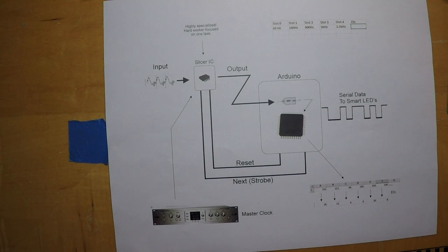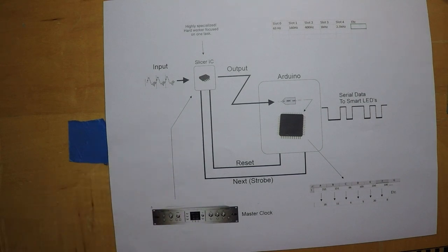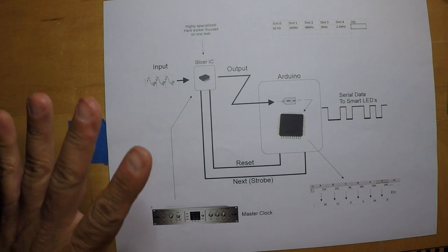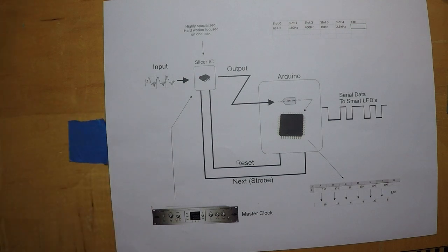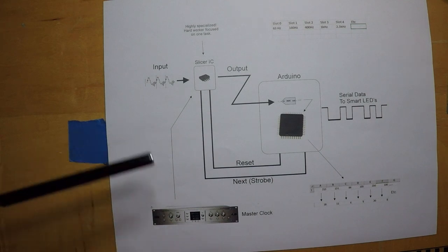I wasn't convinced it was going to remain reliable. Sometimes it wouldn't even start. It wouldn't even resonate, and it would drift. It could drift wherever you placed it. If it was sitting next to a piece of copper, the clock would drift. So for experimental purposes, yeah, an RC clock may be good.